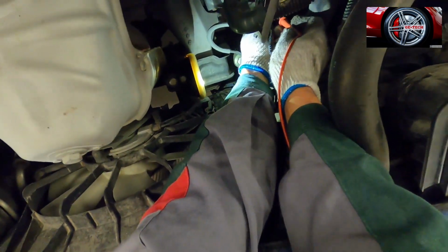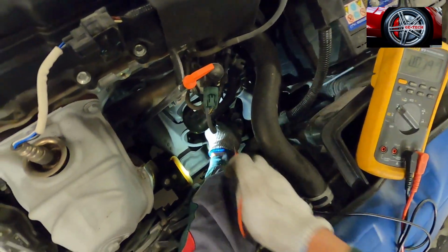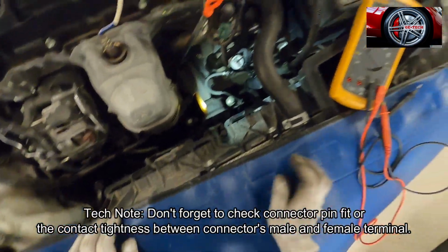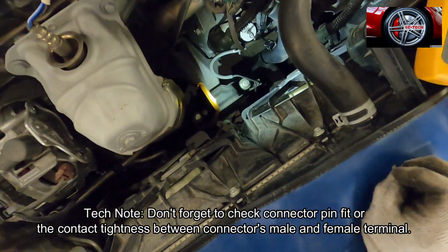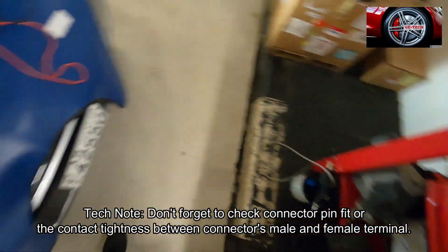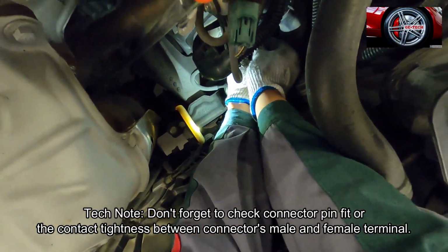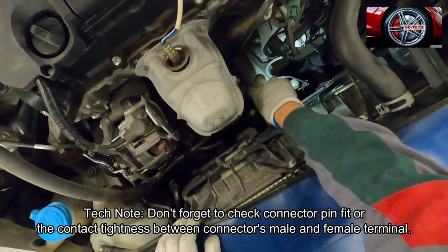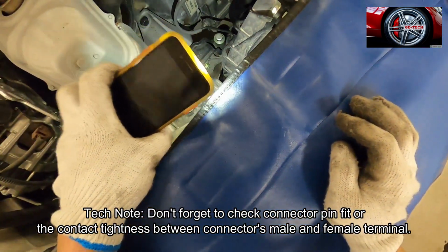So the sensor ground is also okay. Since everything on these three terminals is good, we have 80% suspicion that the sensor is faulty. Therefore we have to remove the sensor and inspect it.